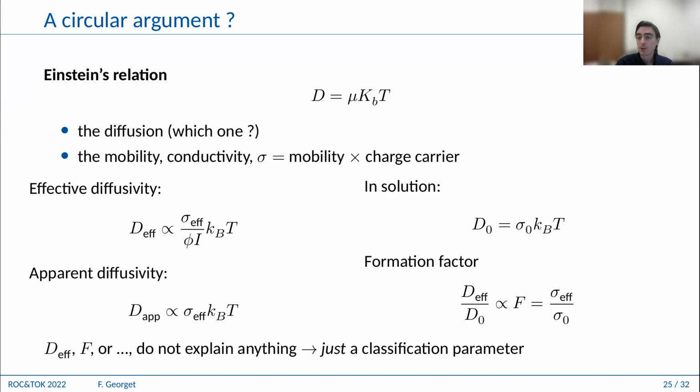So yes, we don't need much more to predict 100 years plus performance of chloride ingress, because we can measure the conductivity at very early age and try to classify which systems are going to be good, and more specifically, compare them to systems that we know work. If your conductivity is lower than a system that you know works, there is a very good chance that your new system is going to be good enough.